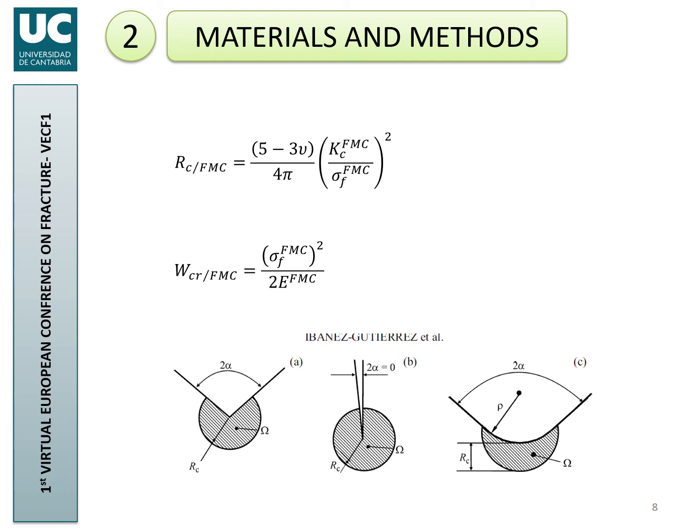Here, just remember that we have to compare the average strain energy introduced in a control volume on the defect tip with the material capacity to store this average strain energy density.